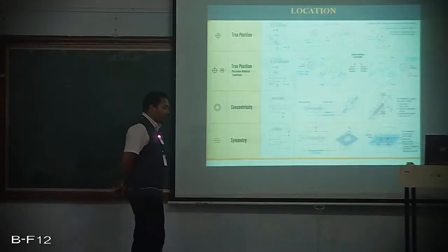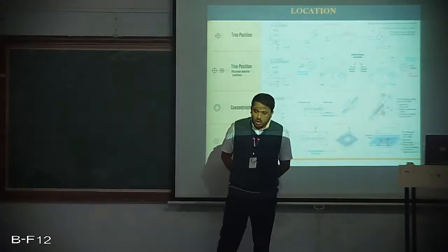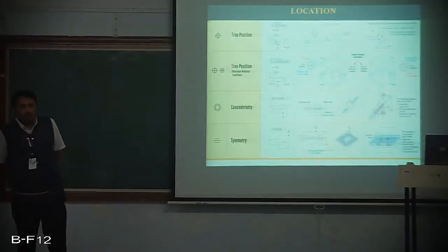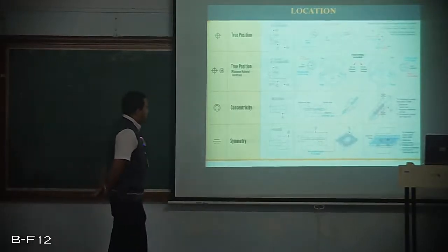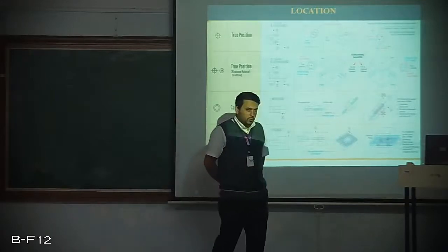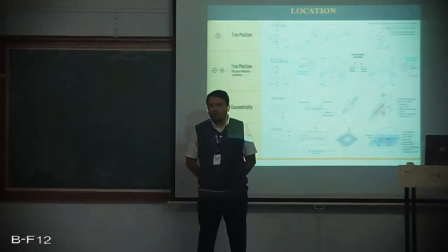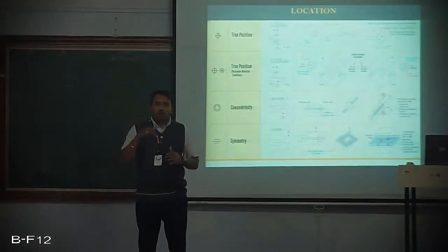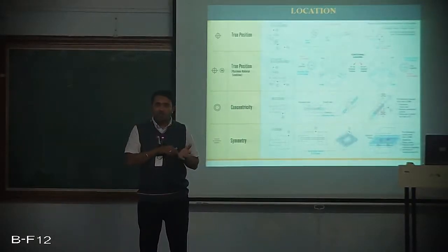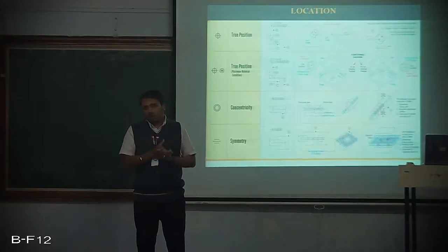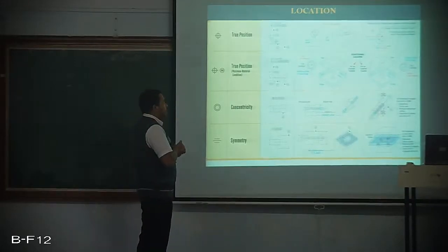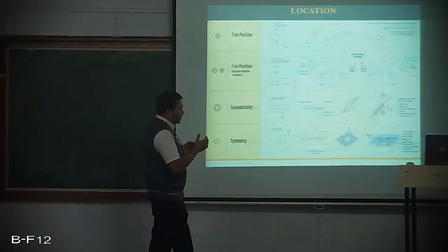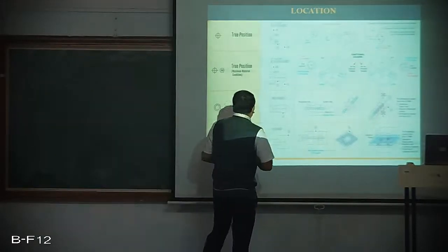If a part has a hole, it may be any kind. It may be a through hole, blind hole, or different types of holes. But there has to be an axis with respect to that hole, isn't it? While manufacturing, if the axis shifts, or the axis must be on the top surface, it will be the center point. If the center point shifts, then what must be the tolerance that must be accepted if the shift happens? That is indicated by the true position.